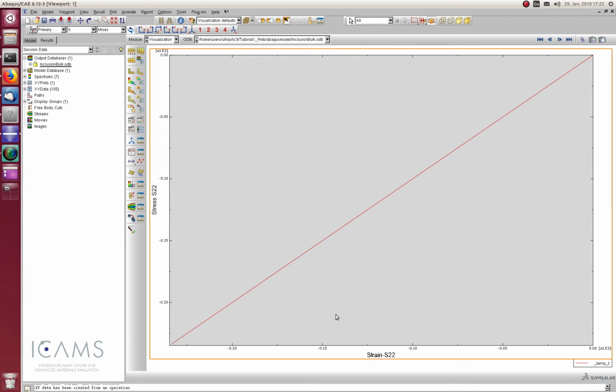And that ends the post-processing, which is a relatively simple post-processing scheme, but I could show you how you can export the different contour plots to a specific file, and how you can extract the data from the database file and do some simple arithmetic like averaging of forces and then cross-plot the stresses and the strains.